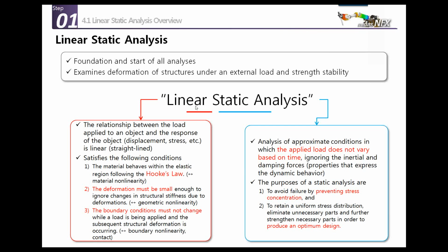A very simple way to remember what linear static analysis is, is to separate it into two things: linear and static. Linear means that the relation between the load applied to the object and the response is linear. For a small force that you apply, the displacement will be proportional. If your force increases, the displacement will increase proportionally. So this is linear. It uses Hooke's law to calculate the material behavior.